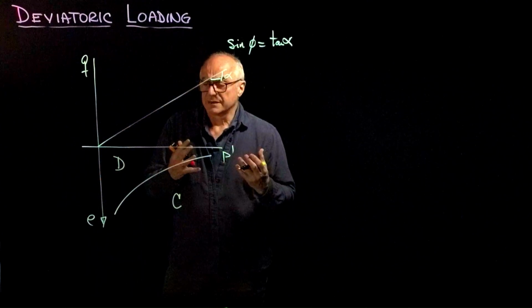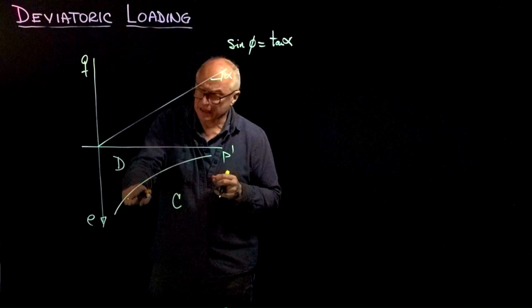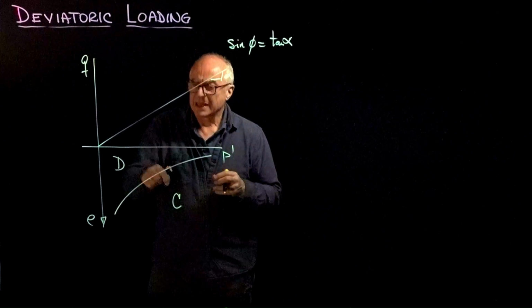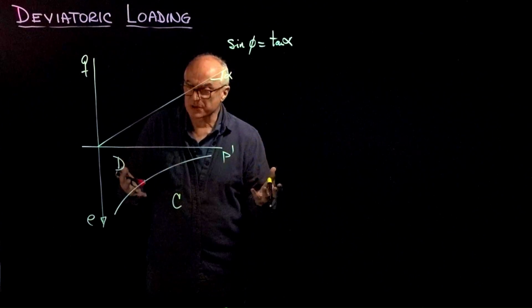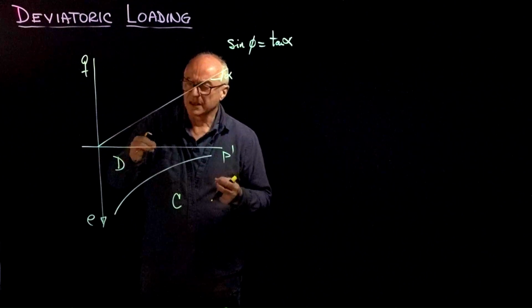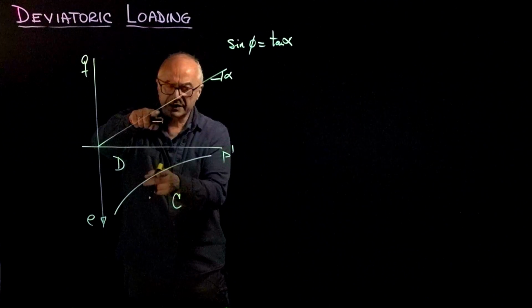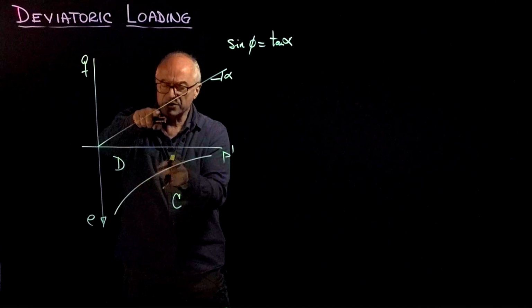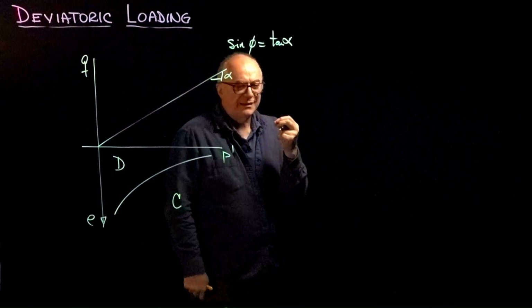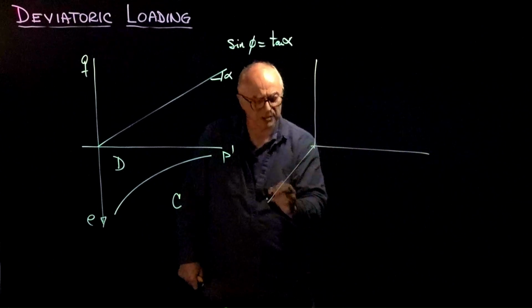Interestingly, all soils will fail volumetrically, will tend to go to this line in the e-p space, the volume-confinement space. From the point of view of shear strength, they will go to that line. So eventually, at failure, a point that represents the soil will be touching that line and will be touching this void ratio confinement line.